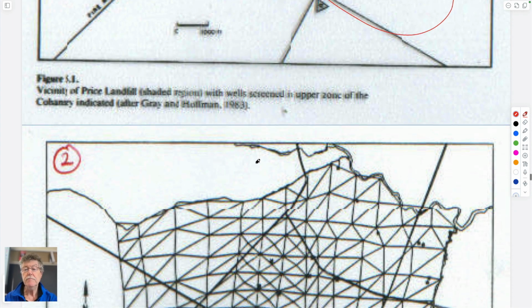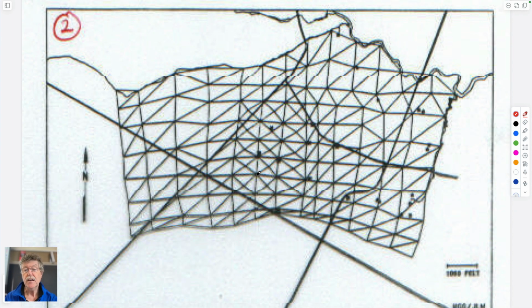So then you go in and you take the site, you divide this plan view into an aquifer of some thickness into the page, and you mesh it out into a whole bunch of nodes which are joined by individual elements. So nodes with intervening elements. Simplest elements are triangles, could be quadrilaterals. And then you try and make a numerical model that takes this and tries to solve the equations for groundwater flow.